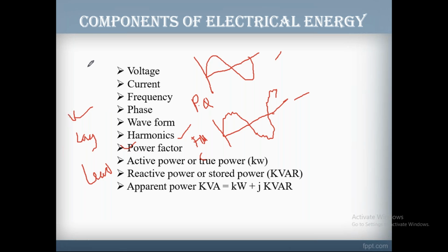When you are using a resistive load, then you will get unity power factor. So when you use a resistive load, it has unity power factor, and it requires less consumption of power. Now the inductive loads are what we use in our homes, like TV, refrigerator, mixie, washing machine. All these devices belong to inductive loads, and these loads have the lagging power factor.